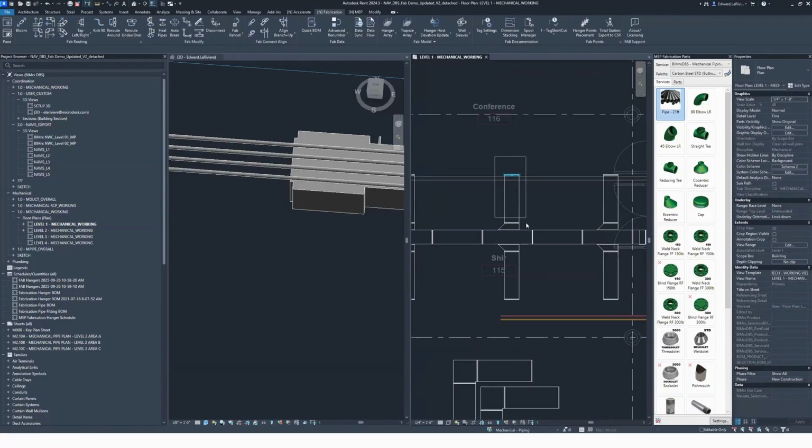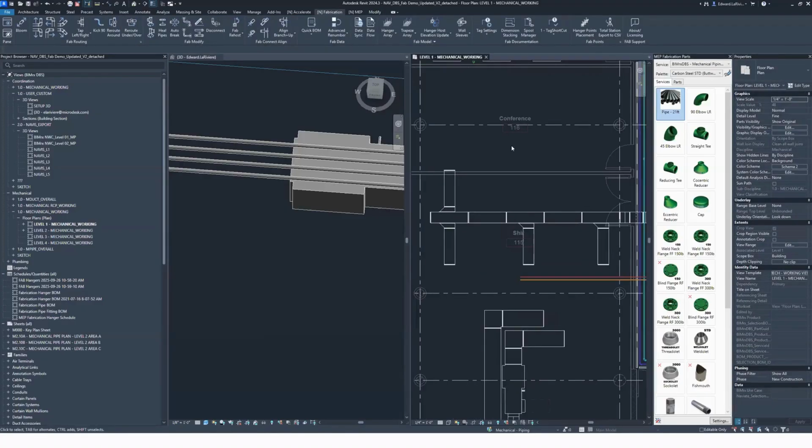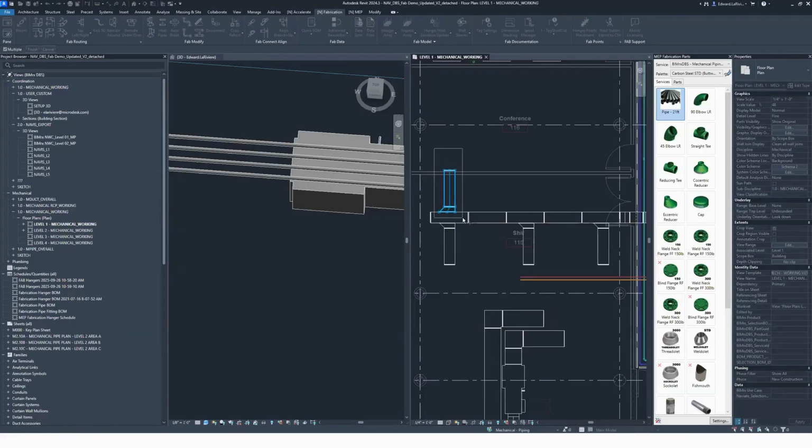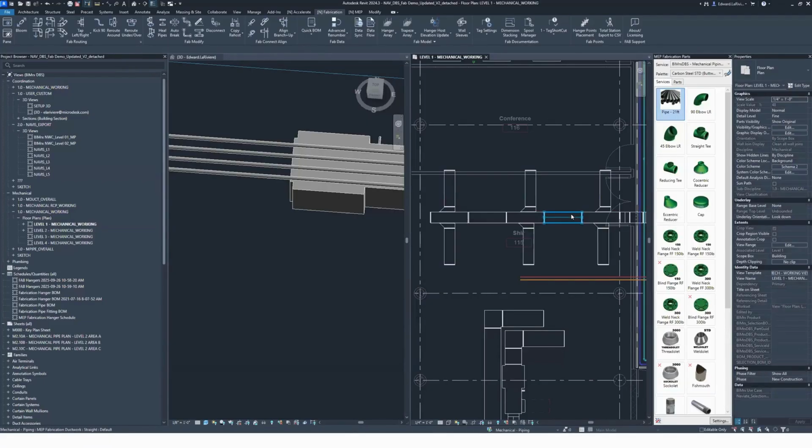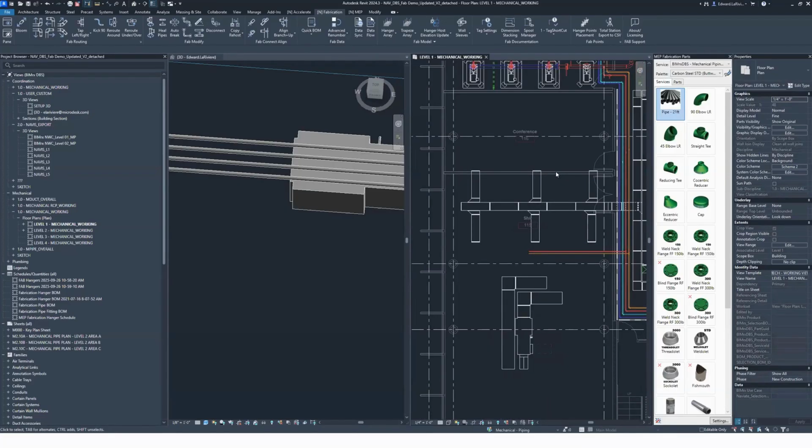And if I decide I didn't want to even do that rehost on all of them, we've got a nice copy rehost tool as well. Letting me jump up, choose the elements I plan on working with, and then just click to place copies of them at each other location. And we'll find that each of those copies placed, again, fully connected together. So if you like that copy workflow of setting one thing up and bringing it through, you can keep doing that. And you can just leverage this tool to auto-connect each one as you go as well.